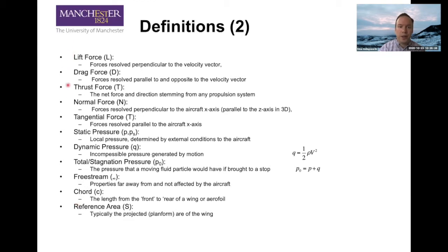And these are really important ones here at the top. The first one is lift force, and its forces resolve perpendicular to the velocity vector. So we tend to think of that as up, but keep in mind that could be any direction. And it's not relative to the body of the aircraft, it's the velocity vector. So when we get to the equations of motion, we'll talk more about that. And we'll have some asides where we look at the aircraft or the glider and how that works. Drag force is just forces resolved parallel to and opposite the velocity vector.